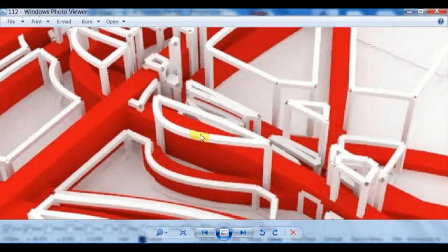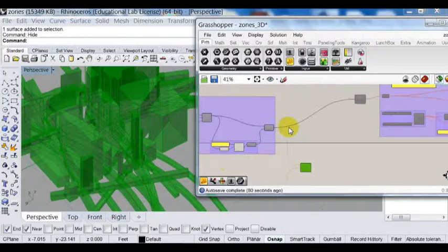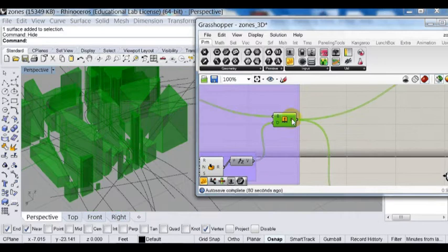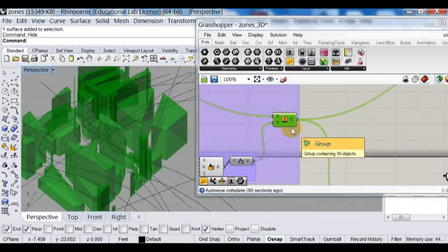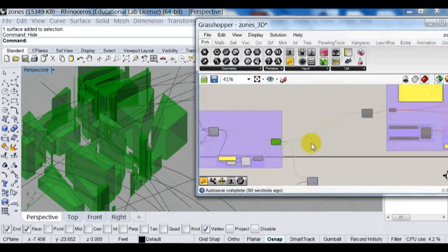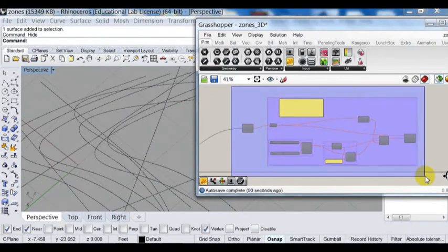And that's pretty intense computing. So here in Grasshopper, I want to do the same thing, super extrude. Okay. So what I will do is I will take only the massing, the building, which is half of the original model, and I will feed it into this new process. Let me just enable this.